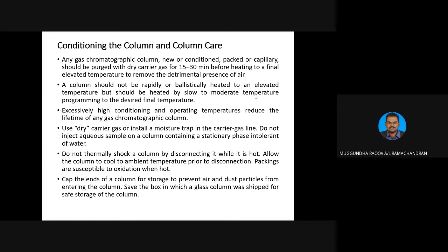Please take note of this. Do not thermally shock the column by disconnecting it while it is hot. We have to wait until the column temperature cools down to the ambient temperature, and we must make sure all the conditions of the GC are okay to switch off. Usually we will wait until there is a green light in the software. The software will show that it is now ready, and then you can shut down.